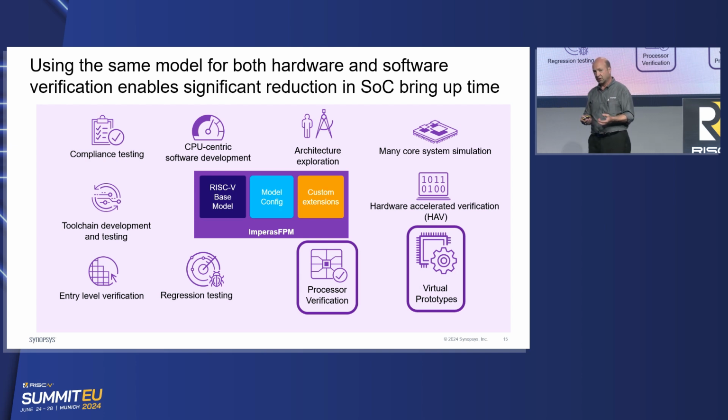So specifically, maybe an extreme case, but we had one user that built a virtual prototype. Well, their platform was, I think, 4 different RISC-V processor cores, doing everything from microcontrollers to application processor to AI accelerator, over 150 different cores on that. They were able to simulate, they were able to do DV, and when first silicon came back, this came up in the lab in a matter of days, not weeks or months, but days.